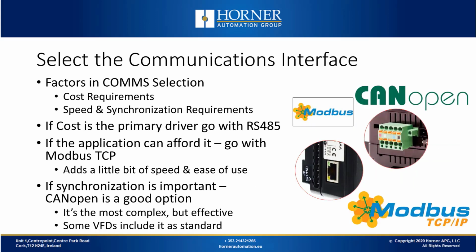The next step is to select the communications interface. There's no ironclad requirement that you connect a communications interface between the drive and the OCS. You could strictly use an I/O connection, but we strongly recommend that you connect to the network. Which network you choose is your choice. You could choose the RS485 Modbus, which is built into most drives. You could choose an Ethernet based connection like Modbus TCP, or a fieldbus type option like CANopen.